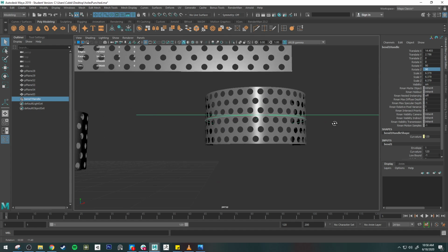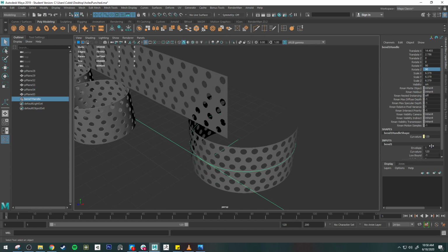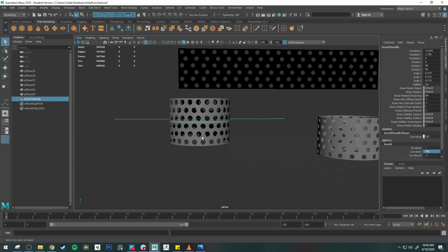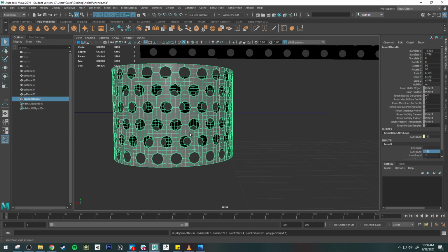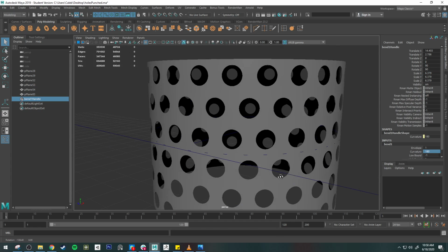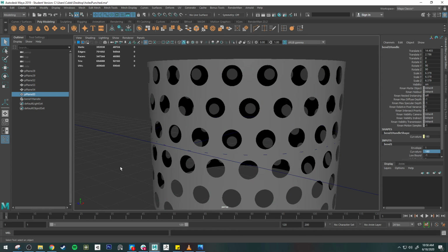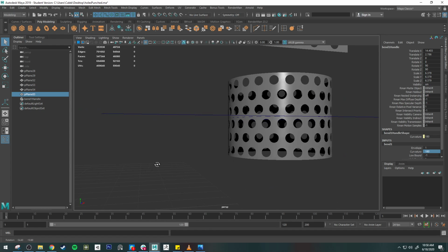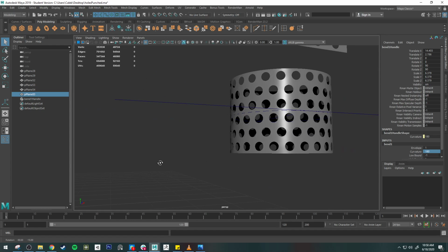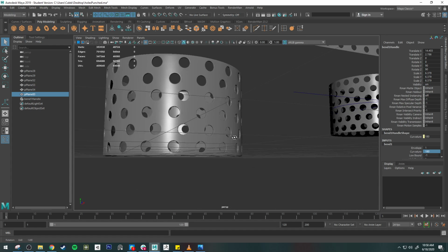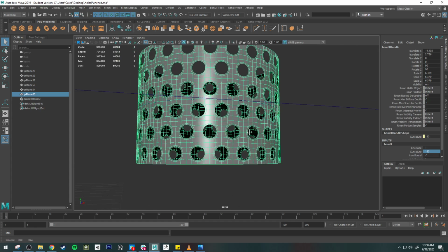Problem is, I need it to bend all the way around. So I'm going to set my curvature to 180 degrees, and you'll see that wraps all the way to the back side. Right? I'll have to merge these back faces in a second, but let's go ahead and assign a blend material just to check my shading, and it's pretty good. It's not bad. It's probably similar or comparable to this one in terms of distortion. So I think that's good.